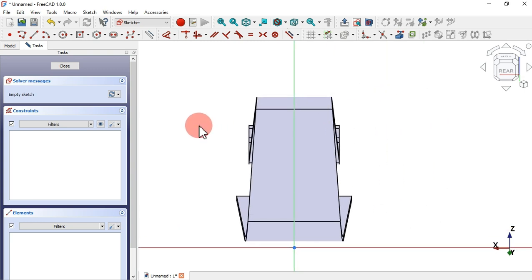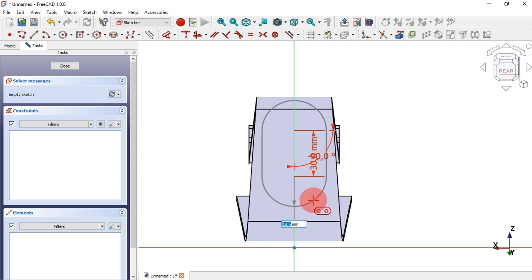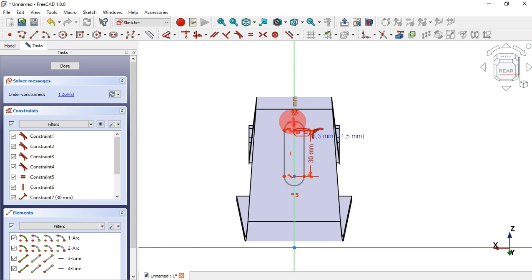Here, what you'll do first is to go to sketch jumps and select slot tool, this tool here. Just click here and start the creation of this slot here on the vertical axis. Set the length for 30 millimeters and the angle set minus 90 degrees, and the radius of this set 6 millimeters, and we have this 1 degree of freedom.